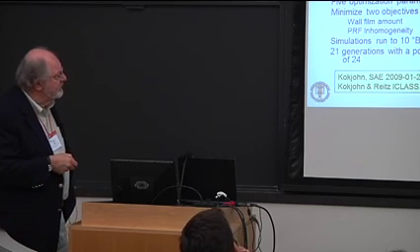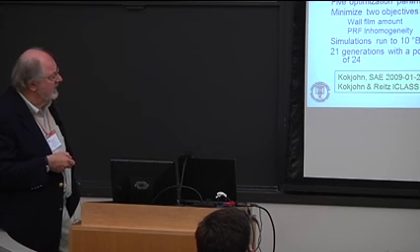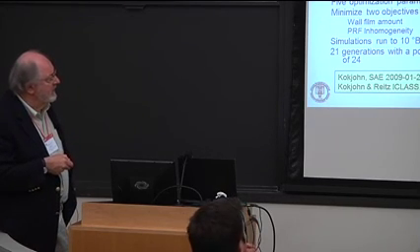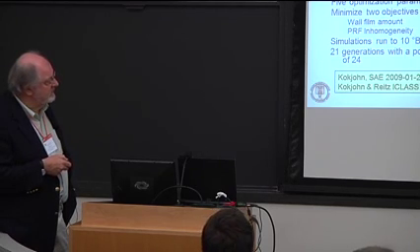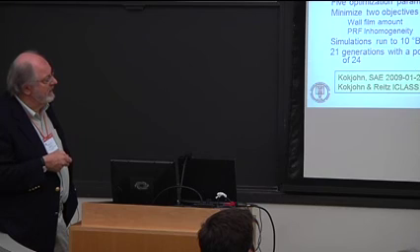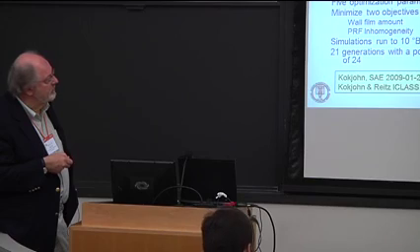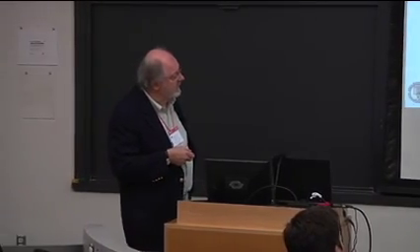And out of all the results, we could pick several of these Pareto surfaces, but we picked one that seemed to have reasonably good results. Only less than 0.5% of the fuel was in the nature of a film of fuel on the walls of the chamber. And the PRF inhomogeneity, which is measured this way, here's the PRF number of each computational cell. Here's the global PRF that we set to 65. And we looked at the standard deviation. And that gave us a measure here of sort of the best mixing that we could do of these two fuels.